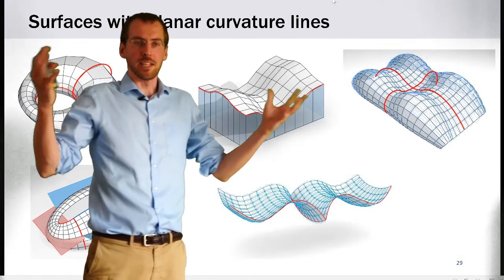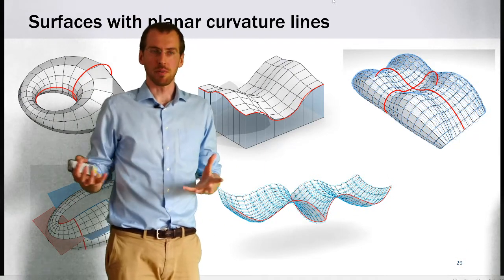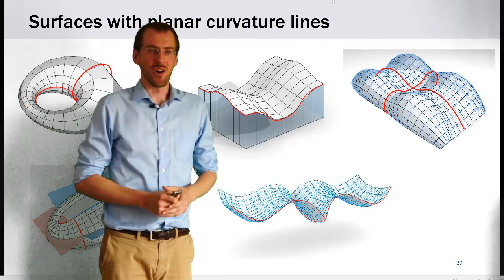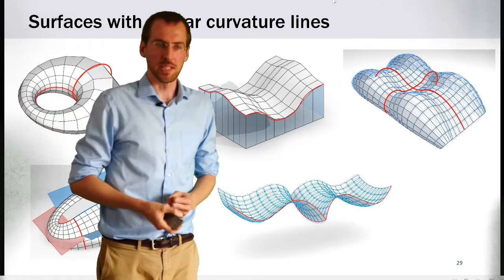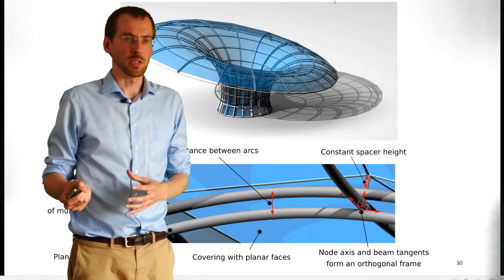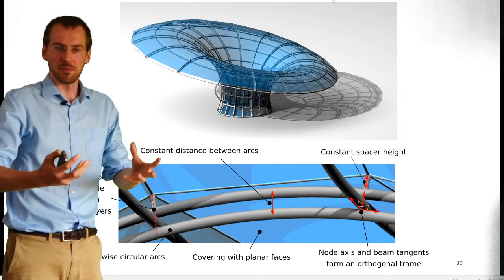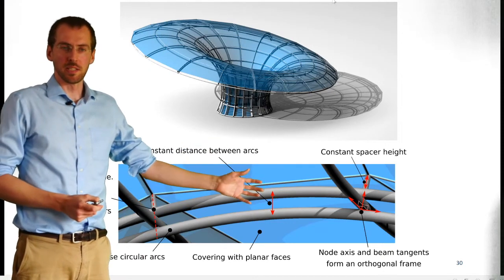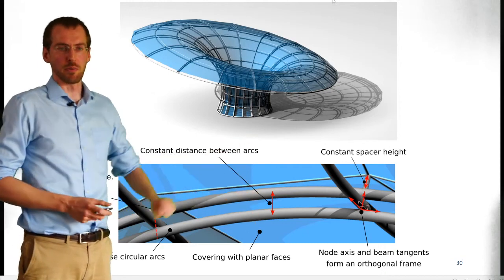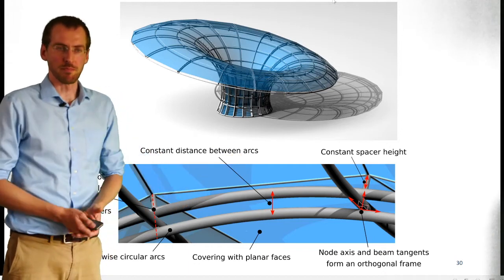So here's a variety of surfaces you can obtain with this method. You can get well-known families of surfaces like Dupin cyclides or moulding surfaces of revolution. And from this circular mesh, you can actually quite simply obtain, in an automated fashion, all the structural details of your structure, for example to do a multiple layer with quadrangles, with standard details, with all the properties that we described before.